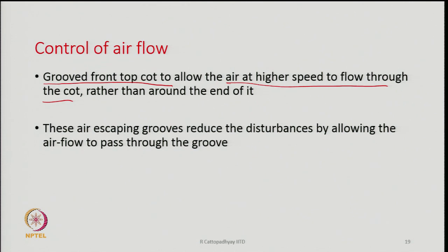So, you allow some air to pass through by having grooves on the surface of the top roller, and that way we can control to some extent the flow of this air along the nip line. These air escaping grooves reduce the disturbance by allowing airflow to pass through the groove.